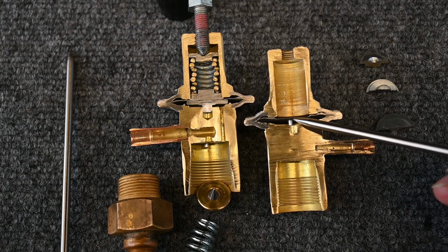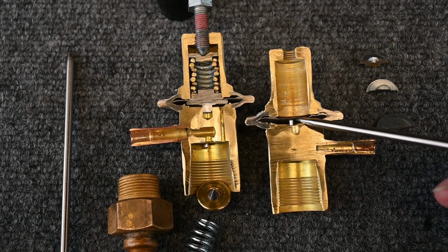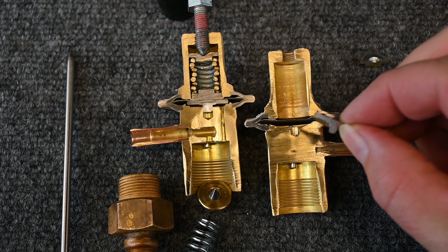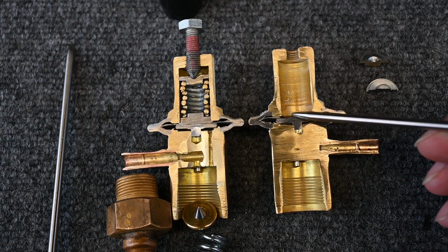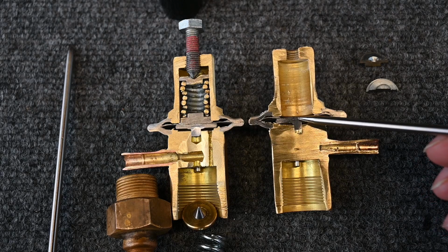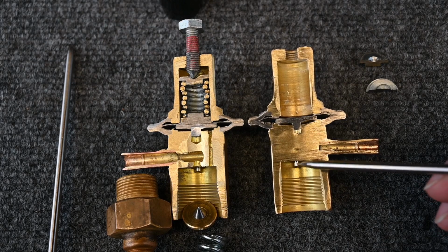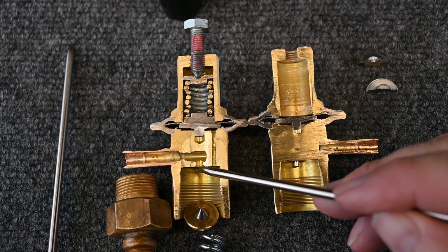But see how thin this metal is? If this piece of metal was pushing against the rods, it would wear a hole in that metal pretty fast. So by having this thicker piece of metal in its place, it allows this thinner plate to evenly distribute its pressure across this thicker plate, and that thicker plate can handle the pressure of these pins on both sides.